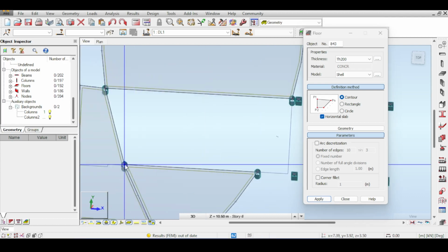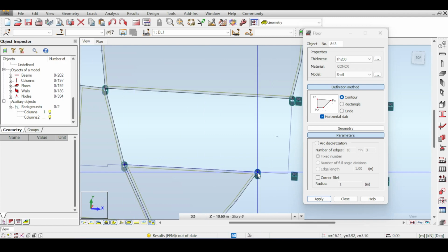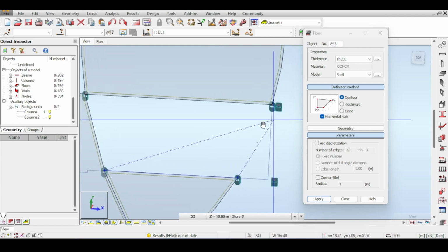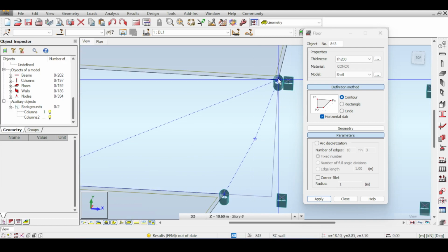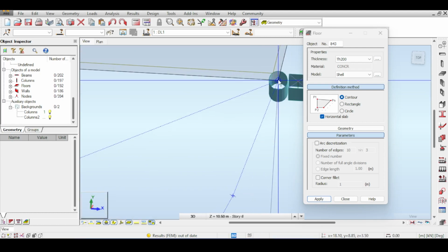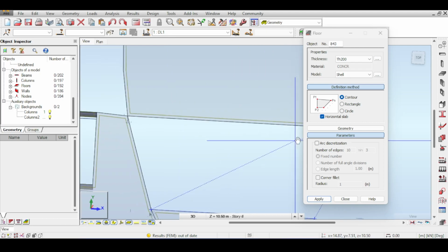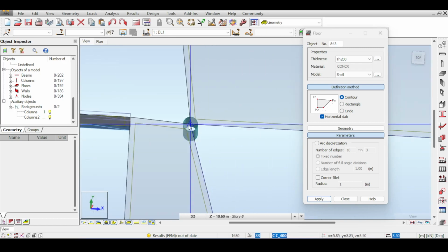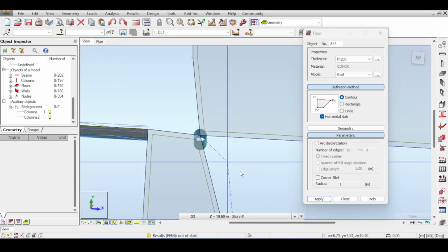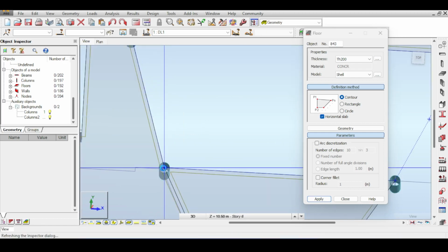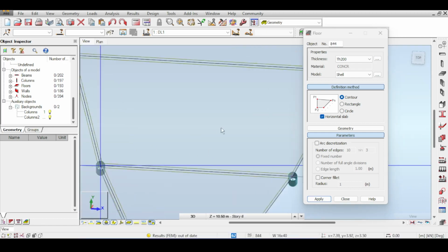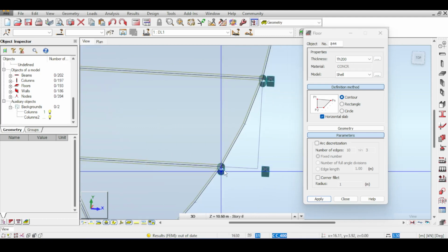So I need to click the first line like this because I want the local axis to be parallel to the global axis in X. It makes my life easier when dealing with the results. I know some of you are Robot pros and they know that they can switch the results to be in the global axis sense no matter what the local axis is, and you're right. However, that's how I roll, so I think I'm doing it correctly.